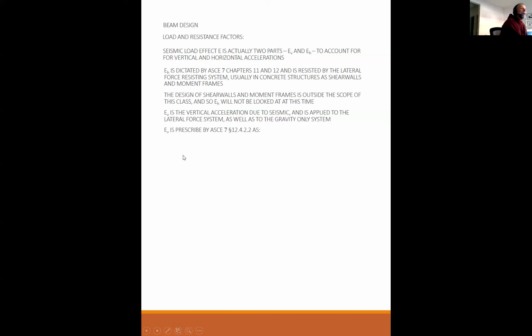E sub V is prescribed by ASCE 7, 12.4.2.2 as 0.2 S sub DS times D, where S sub DS is the design spectral acceleration parameter given by ASCE 7, 11.4.5. This value is required to be calculated and reported on the structural drawings. So on all projects across the United States, the structural drawings have to have the SDS factor on the cover sheet someplace, unless you happen to be in one of those states that just said, oh, we're not going to worry about it.